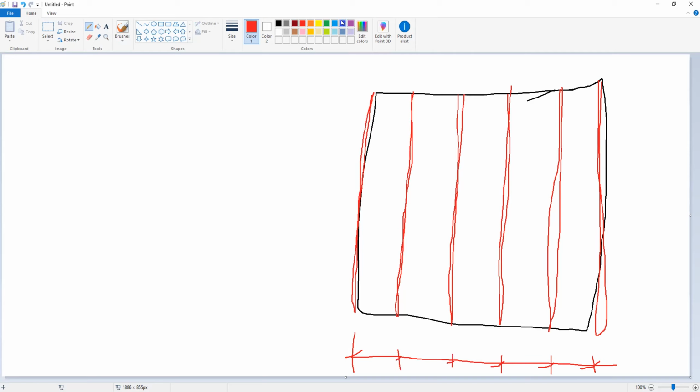Each purlin carries half the area from the left and half from the right. This is called the area method, or approximate calculation method. Each member should carry half of the area from the left side and half of the area from the right side. So this purlin carries all of this area.